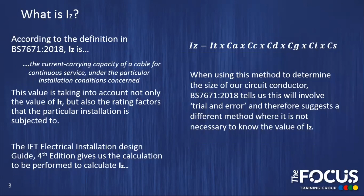How about IZ? Well, again, according to BS 7671, IZ is the current carrying capacity of a cable for continuous service under the particular installation conditions concerned. This value not only takes into account the value of IT, but also the rating factors that the particular installation is subjected to. The IET Electrical Installation Design Guide 4th edition gives us the calculation to be performed to calculate IZ.